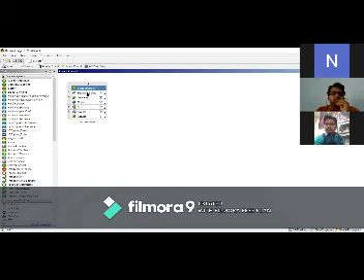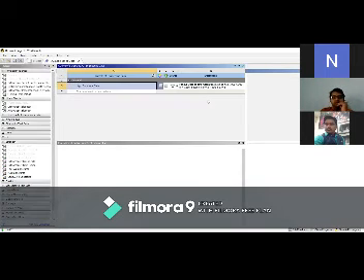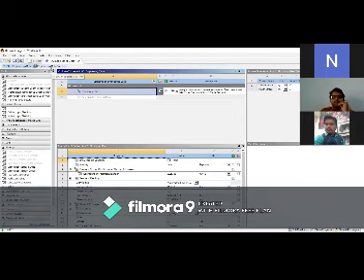Okay, so first, engineering data. What is the meaning of engineering data, and why do we require it? Because engineering data has a directory of the materials involved inside the Ansys software. We can see a number of materials here. Click on engineering data, and we clearly see the material structural steel. In Ansys, structural steel is selected as the material by default.